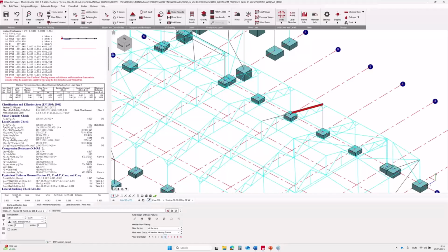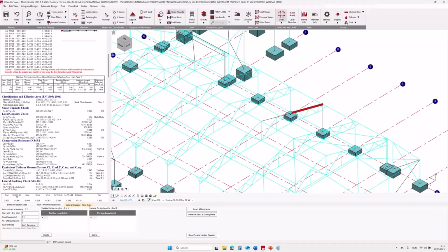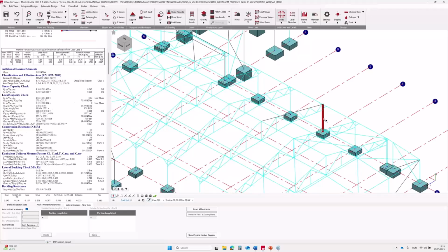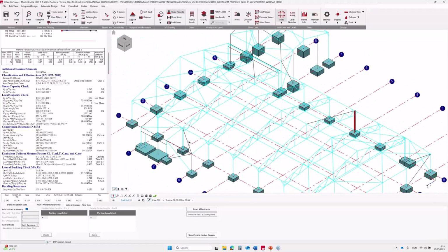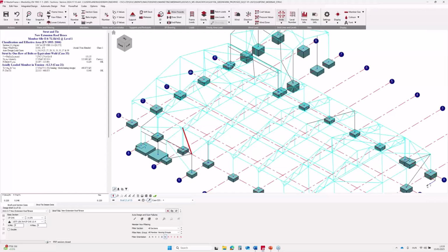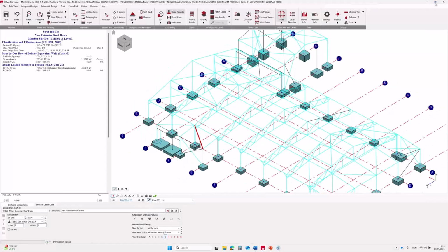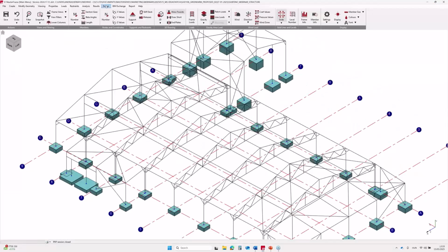For beams, they applied the purlins as lateral restraints, positioned every 1.5 meters on the members. For the columns, they only used the incoming members as lateral restraints. To the bracing elements, the strut tie check was applied. Okay, let's move on to the steel connection design.